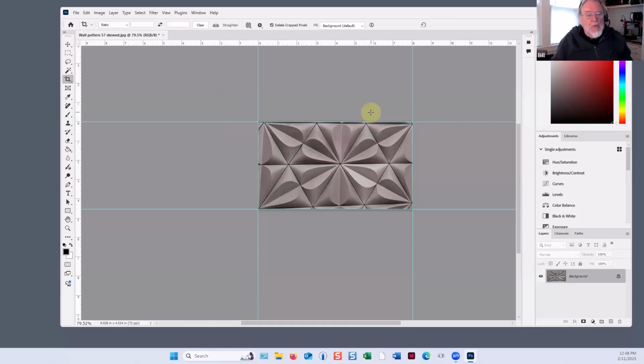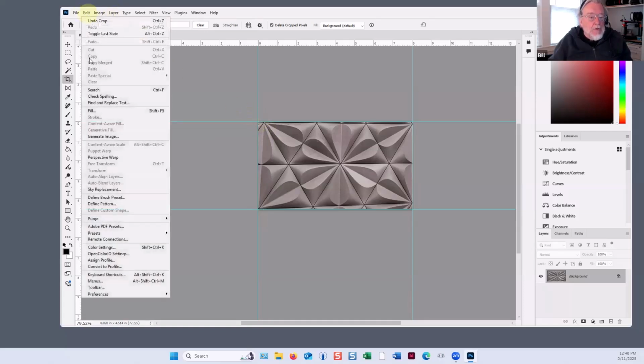And now remember when we were putting those windows into the front of the Sacred Heart School, we used the Skew tool to fix the windows in their new positions. I'm going to use the same thing here to line these vertical image lines up with the rulers. So that's an edit.